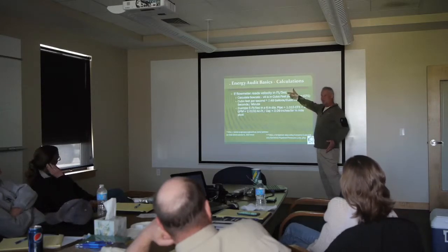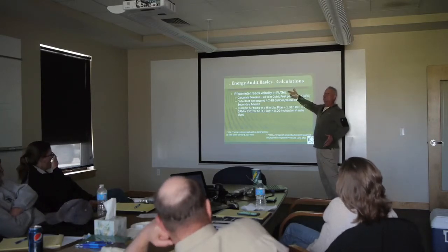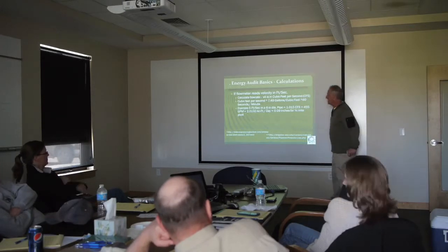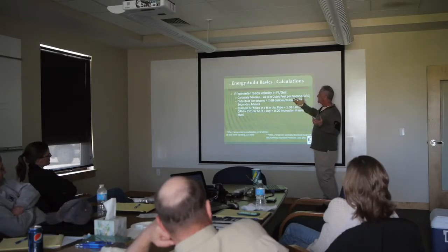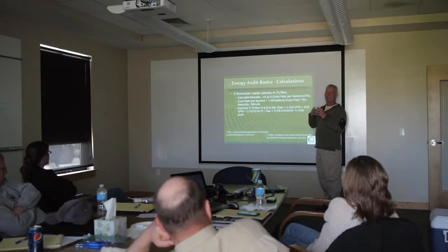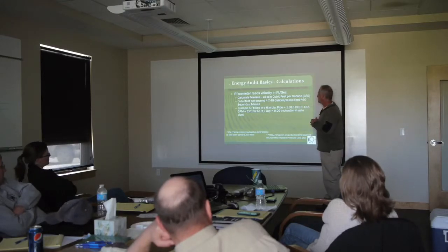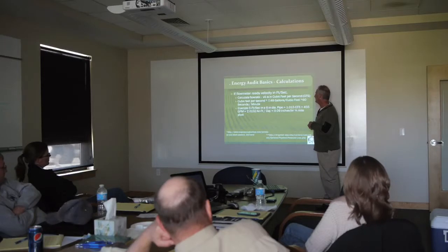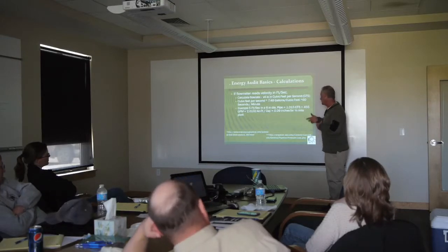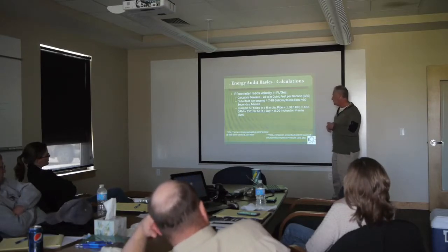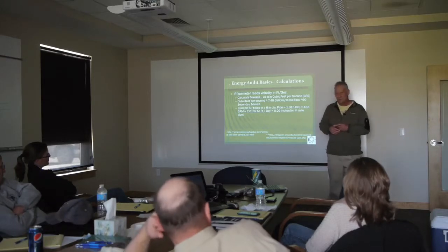Okay, so here's calculations, the flow meter, and this flow meter does this calculation for you. But the flow meter, I thought, read in feet per second. And I think you can probably tell it to give you the reading in feet per second, but you put the pipe size into this flow meter, and then it calculates the flow rate. So you don't have to do this step, but you can calculate the flow rate from that. Here's an example. My 6-inch pipe, 5 feet per second, 455 gallons per minute, 2 acre-feet per day, and 1/10 of an inch for my pivot.